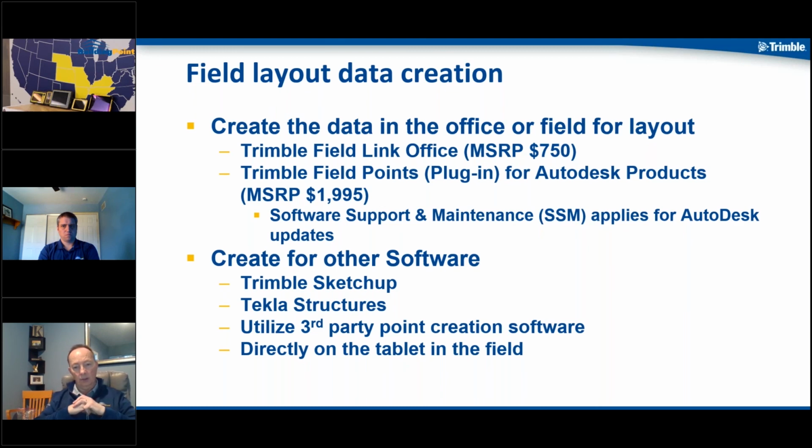So we also have create for other software. We can create data from Trimble SketchUp, Tekla Structures and things like that, third-party point creation software. So there's ways to do that. And then additionally, you can create it just on the field tablet. So there's other ways that we can manage and get that data into the tablet. For instance, if you've got a CSV file that you maybe received, sometimes we get those from surveyors or from engineers. They might create that data some other way and then kick that to you. We can obviously do an import and bring that data right in, and we're ready to go.